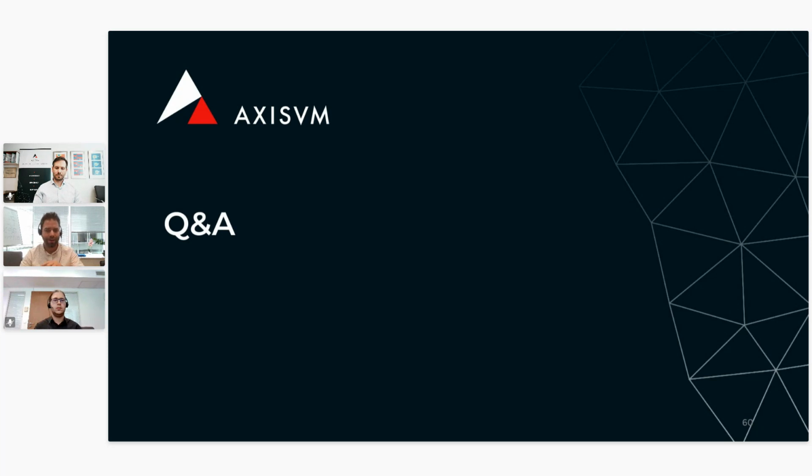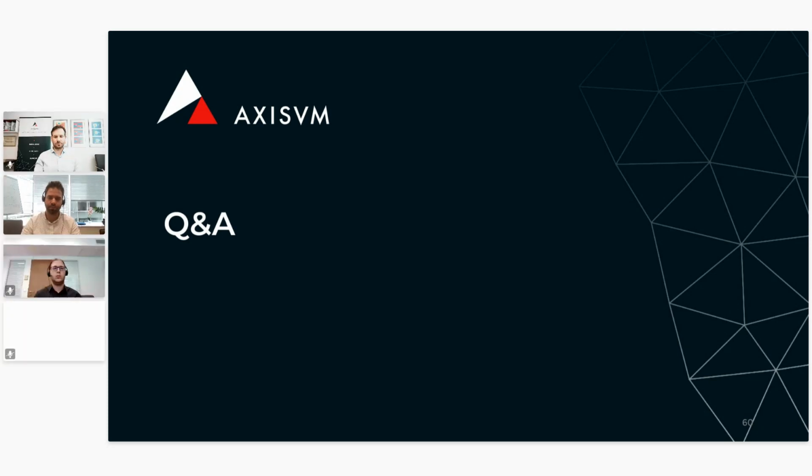You only have to decide what happens first, and the software will automatically insert new construction stages into the manually defined list. So you don't have to create them by yourself. The software will create that for you, but at the end you will end up having just pure construction stages containing one type of action. But you can mix them. The software will handle it automatically for you.